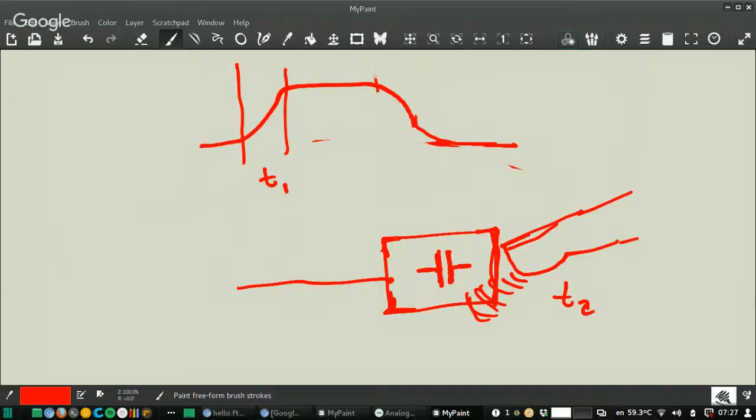And then if you are even touching, not even close, but touching now, you will measure another time, T3, for this to charge. And then with these values of time, you have to create a program that says you are touching the step response sensor, if it is a touch one.